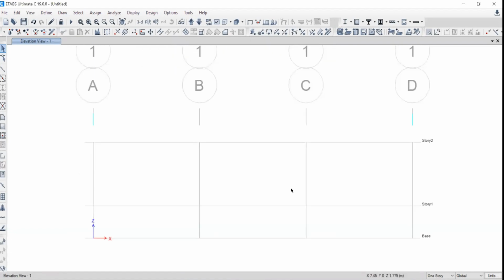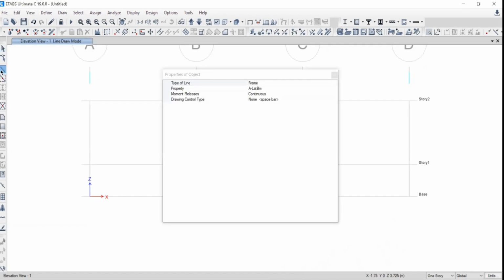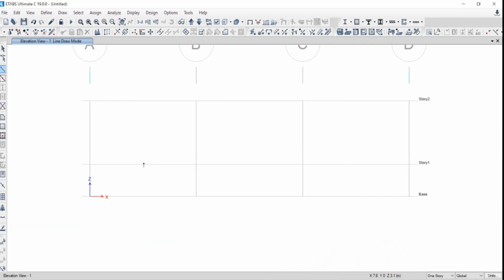Okay, I have to do the modeling of the truss here right now. Now, just go to first, go to take frame. I will explain these things also, but close it. Okay, this is the first point. When you take your cursor to a particular point, you will get this kind of sign, a red sign. Then only you have to click over that. Unless and until you get this reference point, you don't need to click, otherwise there will be chances of error. So I'm taking my cursor here. Okay, so that's good. Then I can click over that. This is the first way.